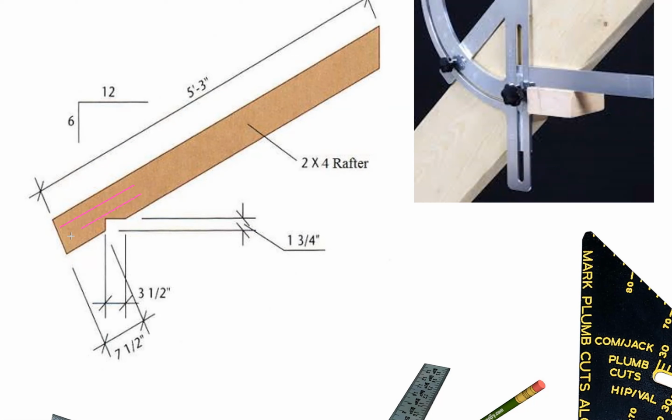You draw the line in until it touches that one, and then come down perpendicular. So you're in 1/3 of the depth. You don't cut all the way in, just about 1/3. All right, so that's the principle there.